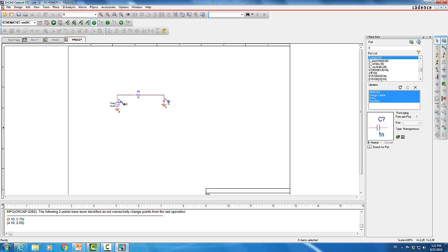What will change here is the frequency of the input voltage, not the magnitude. The magnitude is going to be constant at 1 volt, only the frequency changes. By changing the frequency, we know that the voltage across the capacitor is going to drop, because this circuit is a low pass filter. The low frequency content will have high impedance here, so you will have a higher voltage across the capacitor. As the frequency increases, the impedance of the capacitor becomes smaller, and if the impedance of the capacitor becomes smaller, then the voltage across the capacitor will be smaller.